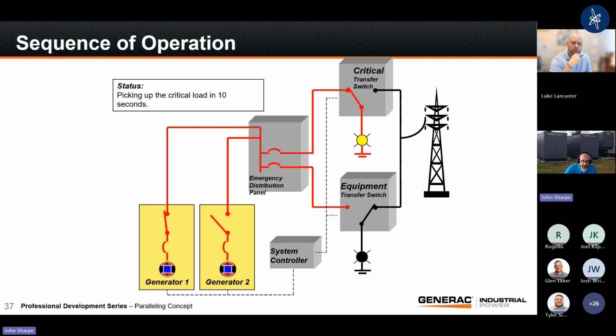And the way this particular system is programmed, we don't want to put the second switch on unless I've got 2 generators. All right, so this becomes a sheddable load based on the capacity of the generation in the system. And this device here, my system controller, is the device that's making the decision to say, hey, you need to wait for a minute. You need to hold on. You don't have permission to go until this guy gets on.